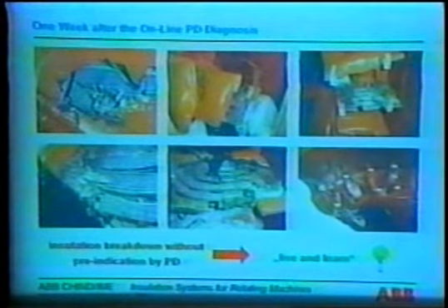This type of insulation defect could not be detected by PD measurements since there were no pulse-shaped local electrical discharges. Instead, this breakdown of the stator winding was associated with continuous leakage currents within the winding, leading to local overheating without any locally high electric field, which is required for partial discharge inception. Therefore, this failure could not be detected.